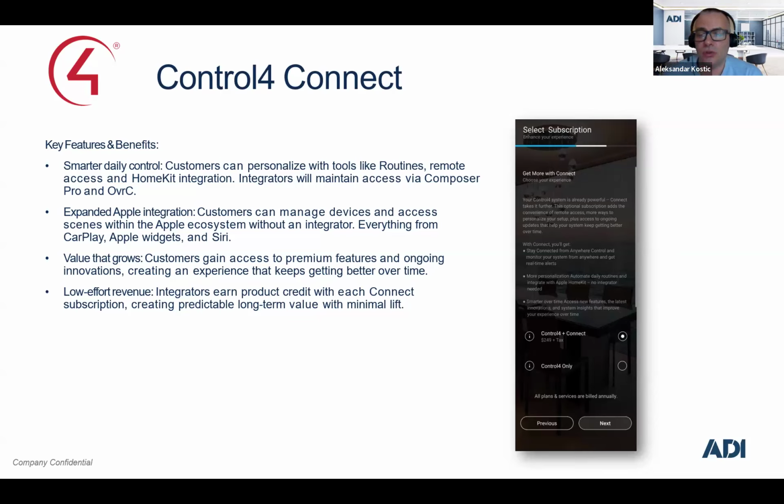T3 touchscreens are also discontinued, so the only touchscreens which you can use currently are T4 on X4 operating system. So generally, we do not require immediately to upgrade your hardware except T3 from EA to Core in order to continue with X4, but with some of the next releases, we expect that EA will be discontinued. So with the first release, you still can use it just with OSD, and with future releases, the core controllers will be required.